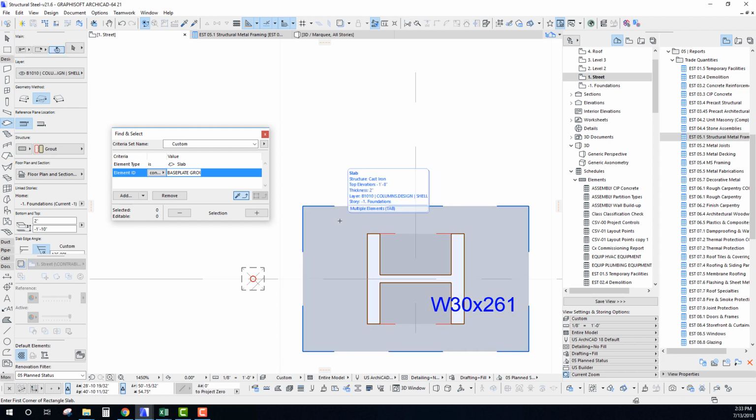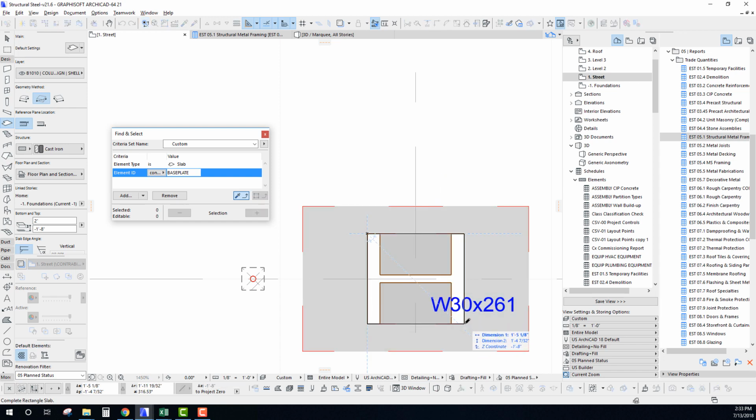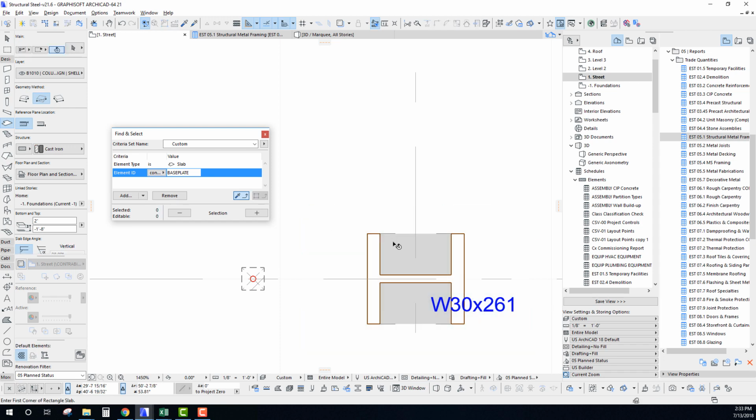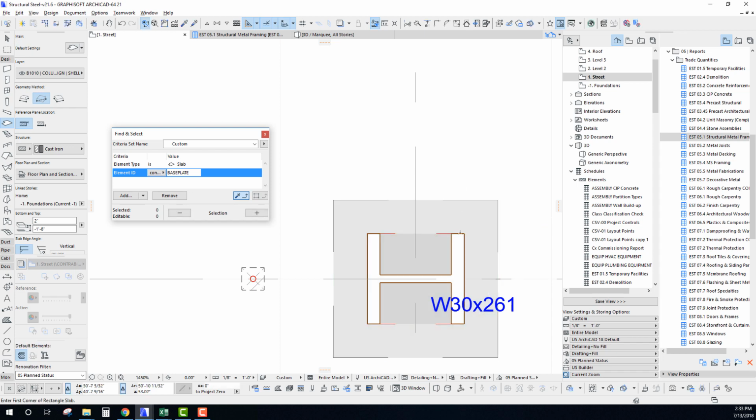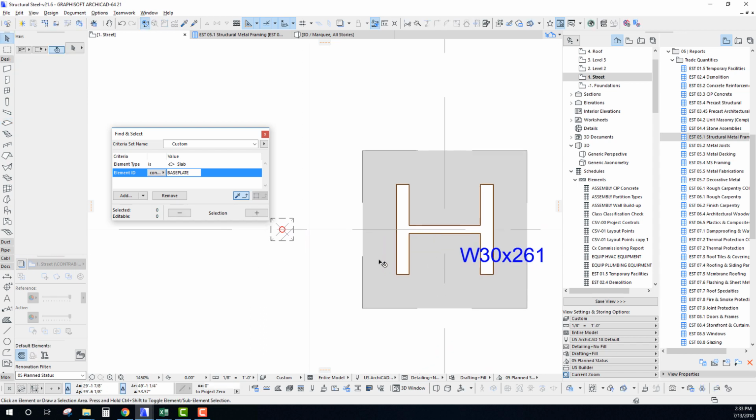And so which one did I copy? I think I copied my grout. So I need to pick up my cast iron. I'm going to pick that up, and I'm going to just do the exact same thing here. So I'm just drawing it right on top of that column right there. And maybe we need, in each direction, I don't know, 6 inches in this case. And so we'll just create a base plate based on that.